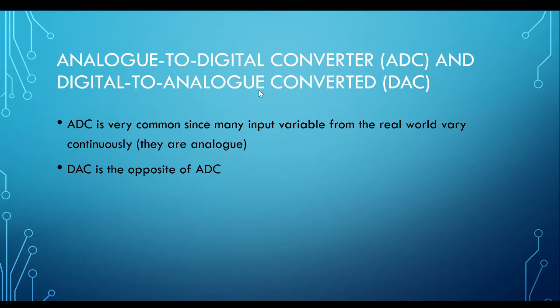Okay. Now ADC means analog to digital converter. I hope you can still reflect back on what is analog, what is digital. Now analog is 0 to 5 volts. Let's say for example my sensor outputs 4.7 volts, in the range 0 to 5 volts, and I need to convert this range into 0 to 255.